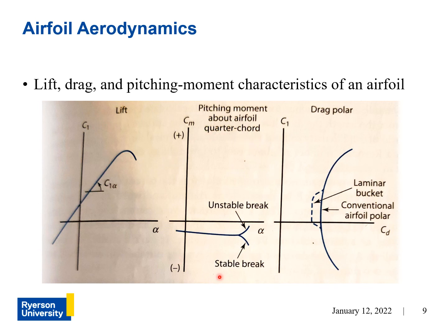Now if you were to find the aerodynamic center for an airfoil that's not that case, it wouldn't be the quarter chord, but the behavior would still be the same. You'll see that it's almost near constant. And this region here, again, is because of flow separation, and that's why it begins to break, and it's for the same reason that the lift here starts to act a little funky, because of the flow separation.